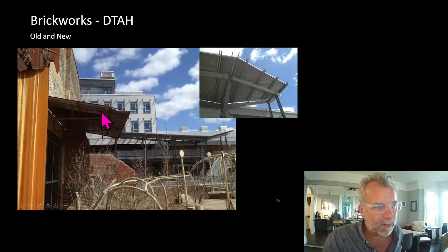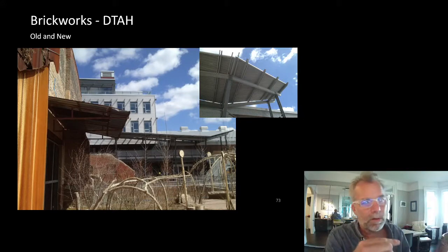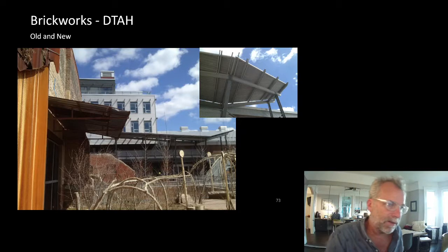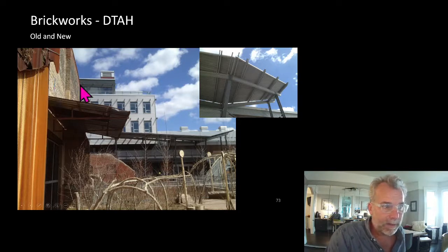It's also extremely light. I think Shannon mentioned that by our calculation, we would have something like 100 pounds a square foot or 5 kPa of snow on this canopy due to accumulated snow. Anytime we've got a high roof and a low roof, we assume all the snow blows off the high roof and accumulates on the low roof. It's obviously not the case, or this would have collapsed, but that's what the code requires us to do.